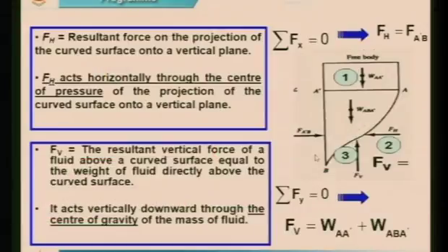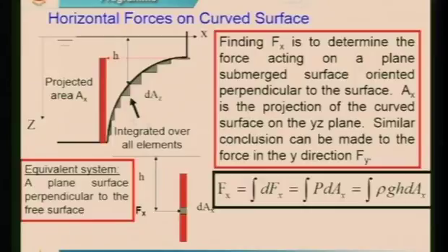Then the second part is the same which I told you, the weight of water over this portion. You can see this portion is having a rectangle here and a small portion here. So what I will do, I will take the volume of this rectangle, I will take the volume of this rectangle also, and I subtract this quarter circle. That will give me the answer, correct.